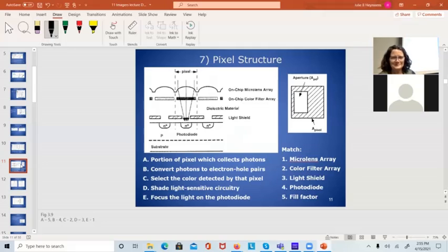Okay. So inside the pixel, we have a photodiode, but that's not the entire pixel. There's area in here that's readout electronics. Why is my pencil not working? So there's area in here that is readout electronics. This is part of the pixel where you're not gathering light.